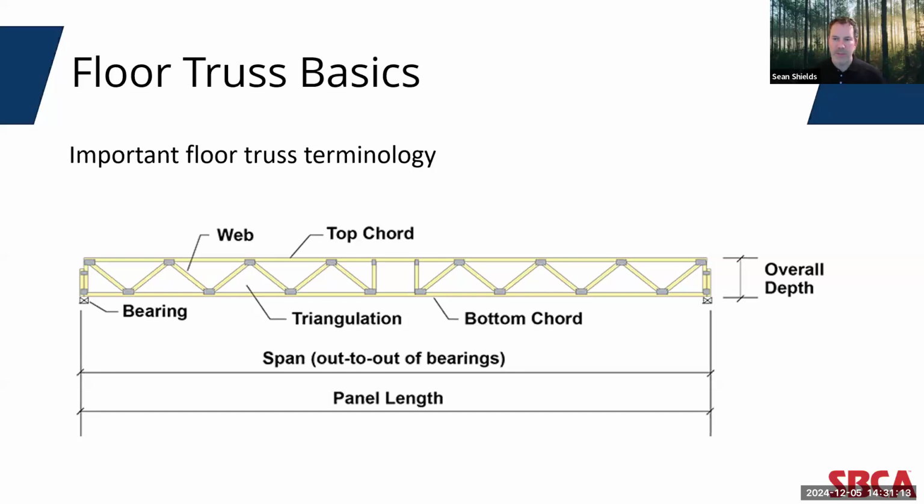Some of those perpendicular webs also provide chase openings. Now, due to the triangulation that's the inherent part of a truss, the depth of the floor truss, as well as the strength properties of the wood used in its construction, play a major role in the distance the truss can span. So today we'll look at a few of the details that cover how to handle bearing walls between two different floor depths as well.